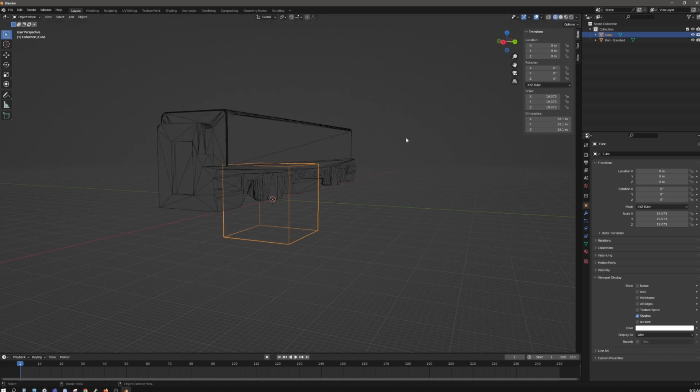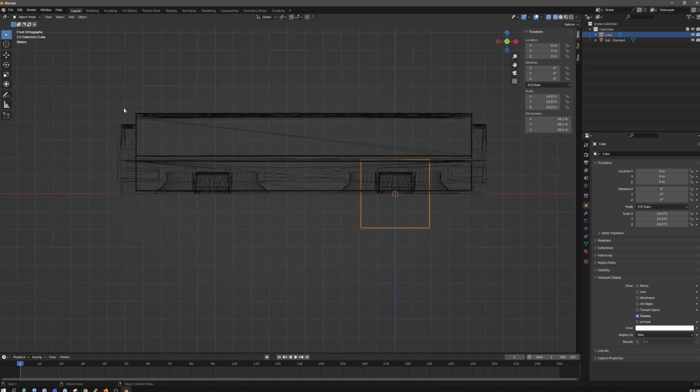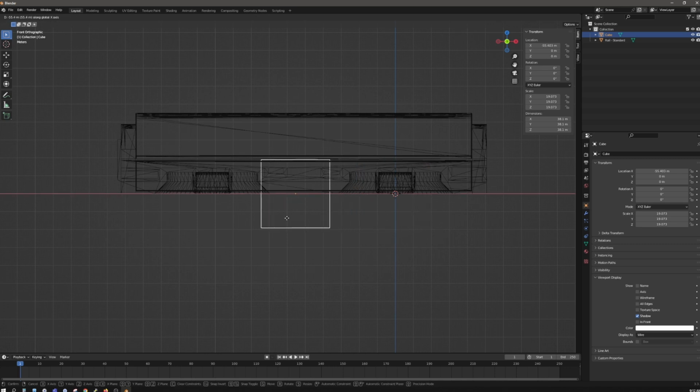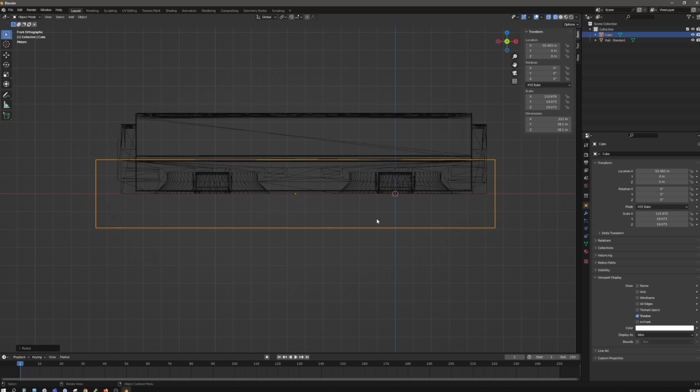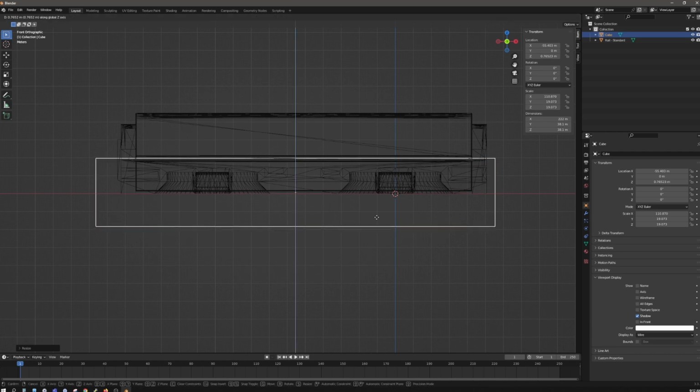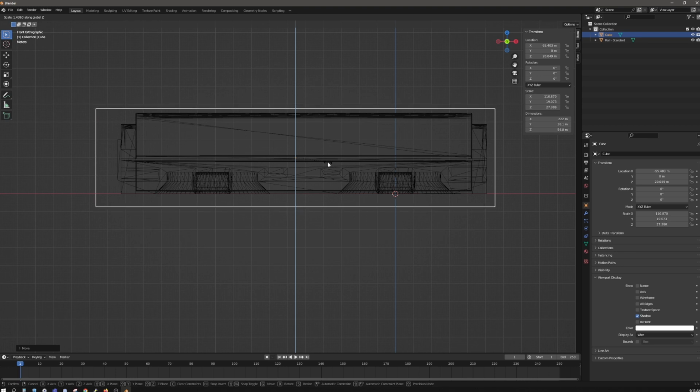So let's go ahead and go to wire view and go to X-ray, get another one, and I want to encompass everything, and I want to chop from this ledge from there up to make it a lid. So we're just going to use our command keys to move it in place. G for grab, S for scale. I'm going to go on the X axis, which is that red line, and encompass the whole thing. All right, let's see what else. I'm going to go ahead and move it up. No, it's not big enough, so scale at Z, go up and down, make it big enough.